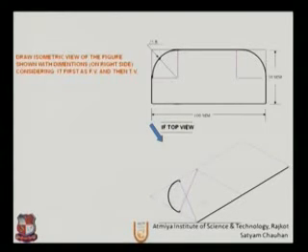To complete this arc, repeat the opposite steps from this point to this point, which will be the bigger arc. Hence we can produce the large arc, same as we learned from the circle, and simply join the remaining lines. Hence the top view will look like this.